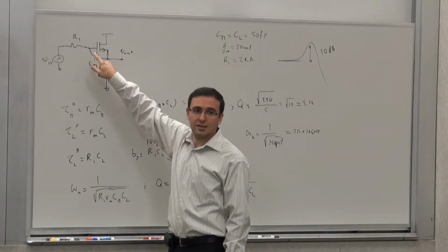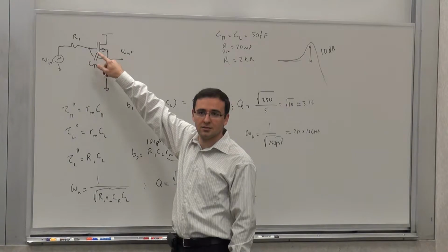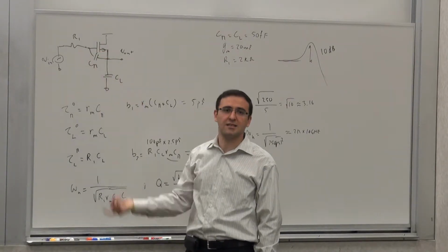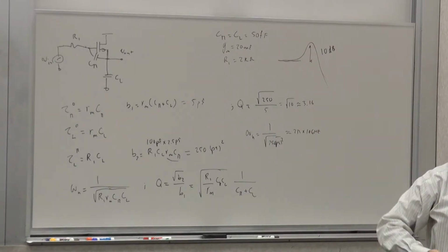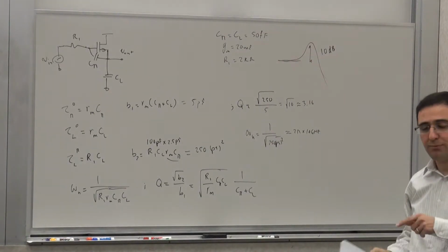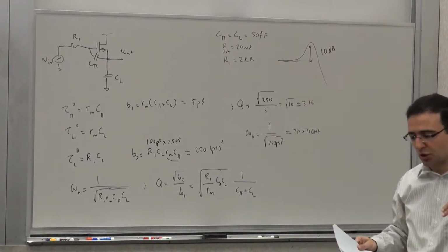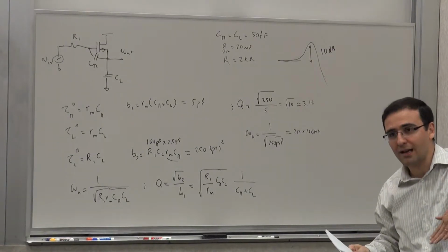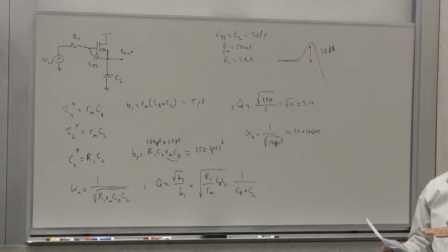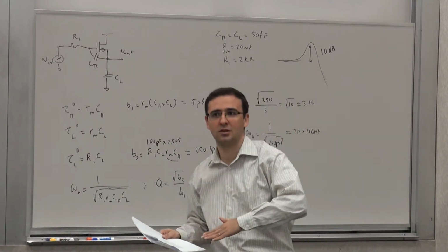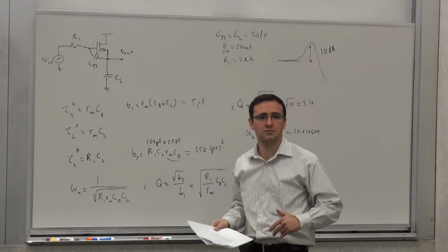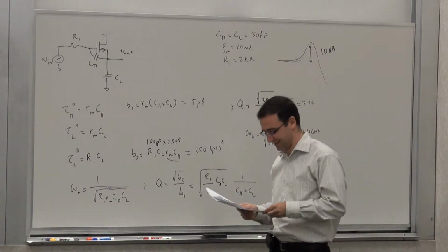When you short circuit this, you have a transfer function with a left half plane 0, so it contributes positive phase. So it brings it back up. And you can even see that in the amplitude plot if you look carefully. You see the slope is higher at first, and then it becomes shallower, a little less steep. So all of that is very consistent, as it should be.